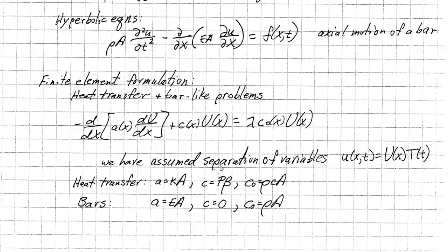And one thing we've done is assume separation of variables. So we take u to be of this form. So that restricts certain physical phenomenon. Particularly, we will normally linearize this problem around an operating point. So you simplify the modal analysis, and that becomes apparent here where we have heat transfer. We're saying that these are linear, or these are constant coefficients, or things like thermal conductivity geometry. This affects your convection on the surface and your specific heat, density, and area.